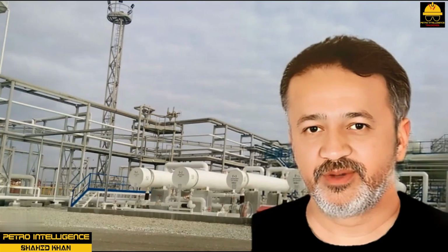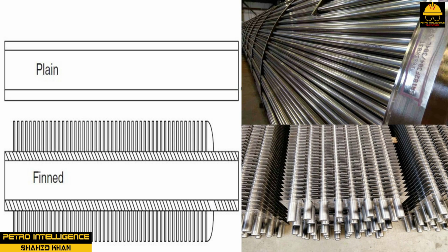Tubes. Tubes on shell and tube heat exchangers can be plain or finned, as shown in picture. Fins provide more surface area and allow greater heat transfer to take place. Fins can be located externally or internally. Although plain tubes are more commonly used in fabrication, the enhanced features of the fin tube are starting to make an impact on new design engineers.